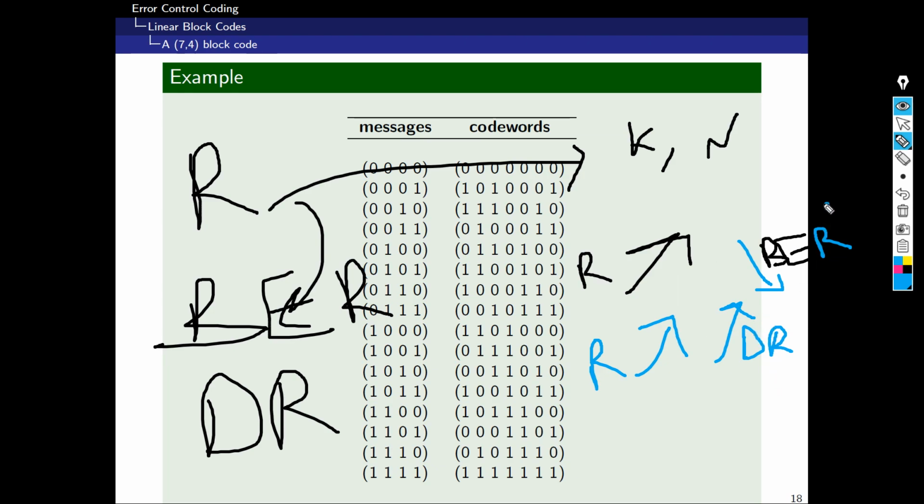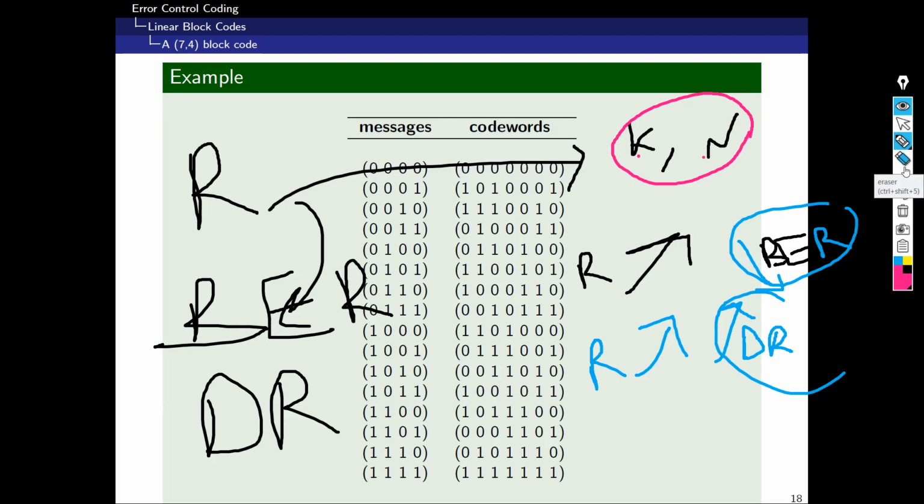How do you control the bit error rate and data rate? You control that by playing with N and K. These are the two important parameters you always need to be careful with, and by using them properly you can always modify your coding rate and accordingly control the bit error rate and the data rate at your receiver side, because this is why we are using coding, to improve the reliability of our system with minimal reduction in the data rate if we can.